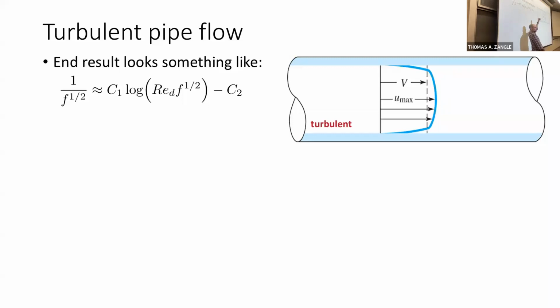Again, we said that we were going to have to find B and kappa anyway, because we made some assumptions that this was going to work for internal flow. And so we've just lumped a bunch of those constants together into that C1 and C2 to make our job of finding these experimentally just a little bit easier. Yeah, and we've also rewritten it in log base 10 because we like to deal with log 10 more often. That's correct. So this C1 then also contains a factor of log 10 over log e.